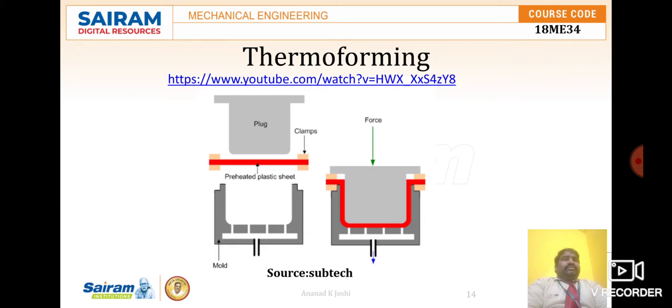In this figure we can see that thermoforming is used to make products like jelly containers in restaurants, refrigerator inner panels, containers or trays, packing units, drinking cups, food packaging and similar parts. Here one is the pressure based thermoforming and another one is vacuum. You can observe both in these figures. For better understanding, we can see a video related to thermoforming. Let us look at it once.